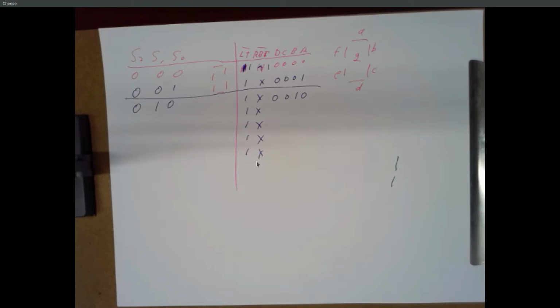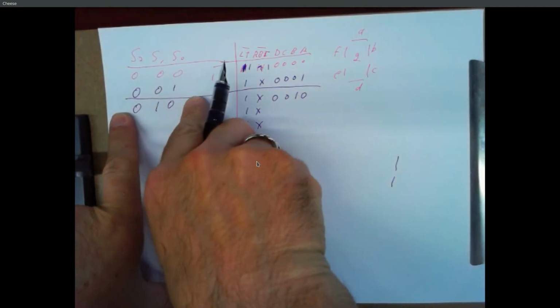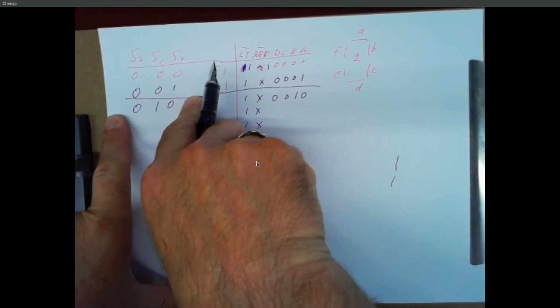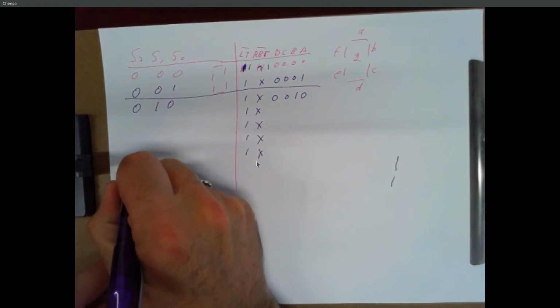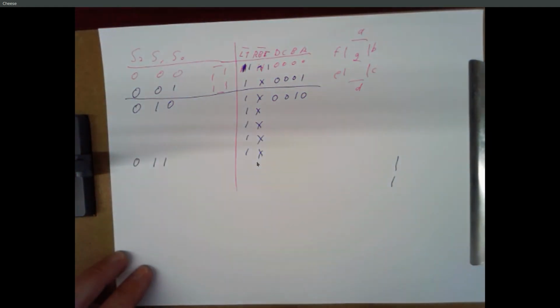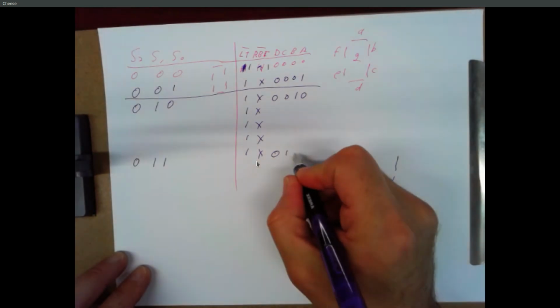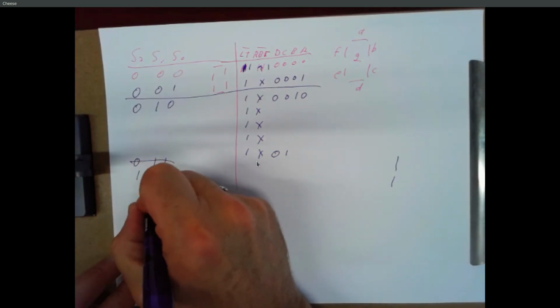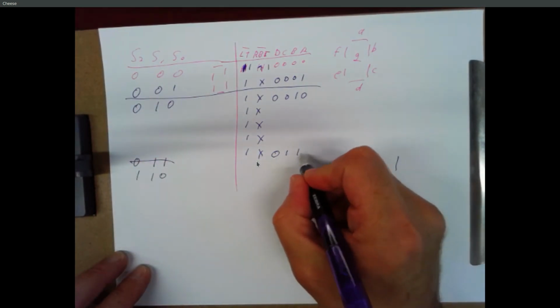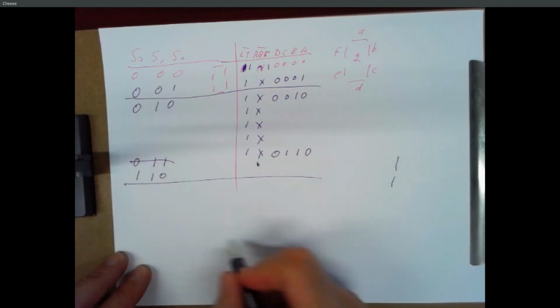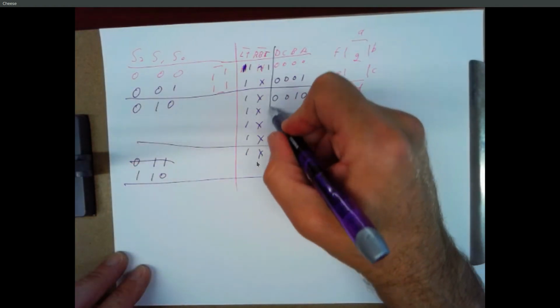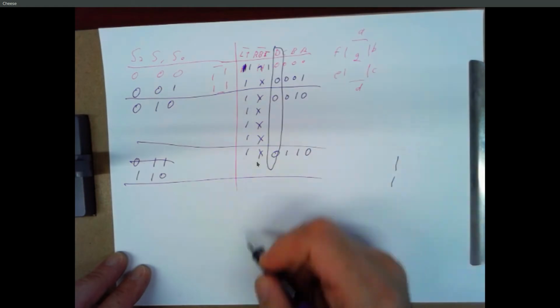That's going to save you a lot of time, because if you forget that, you're going to get weird symbols on your display, right? So what's the largest value that we're going to see on S2, S1, S0? 6, good, because that's 3 plus 3. Right, and so in all these cases, D gets connected to ground.